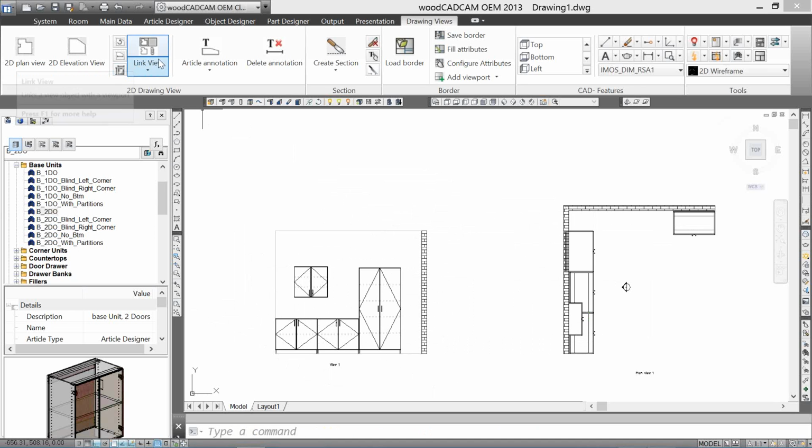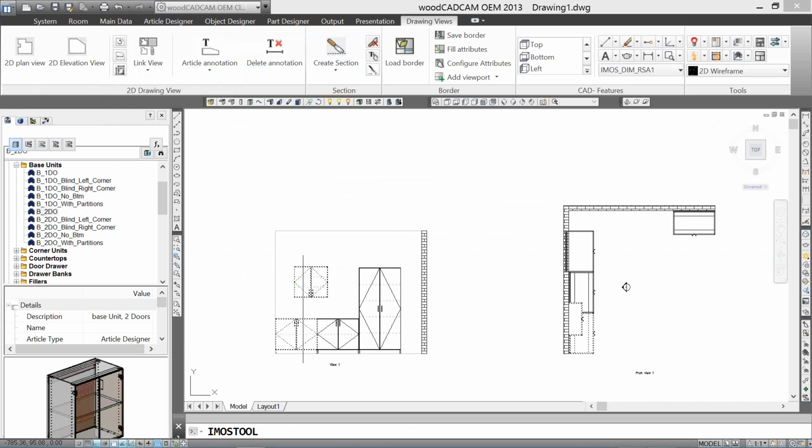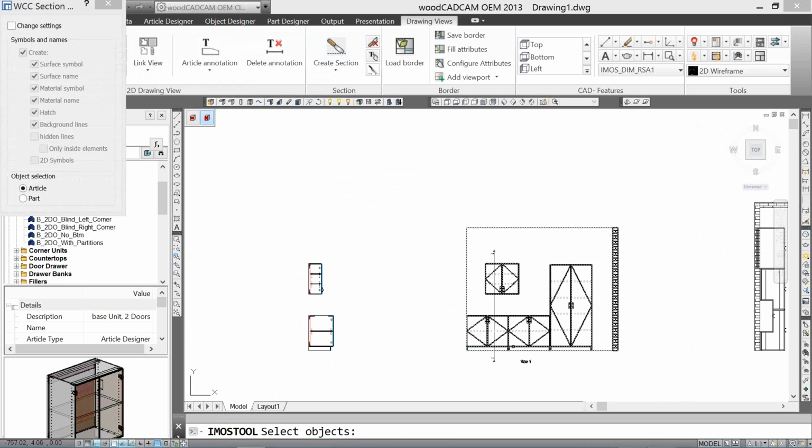I want to go ahead and do some sectional views. So I'll pull a section of this box and this box, and we'll put the divider line right there, and we'll look at it from left to right, and it'll go ahead and pull that. Now some of the other stuff I can't go look both left to right or right to left. In this case I can. So I'll take this other box and I'll cut it and say, okay, let's do this way, and we'll say from right to left.